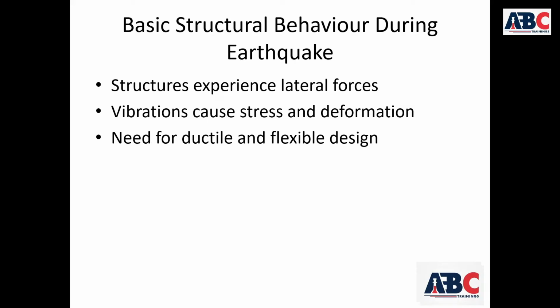Next point is how structures experience lateral forces. During an earthquake, the ground suddenly moves. The building foundation moves along with the ground, but the upper part of the building tries to remain in its original position due to inertia. This differential movement creates internal forces in the structure.